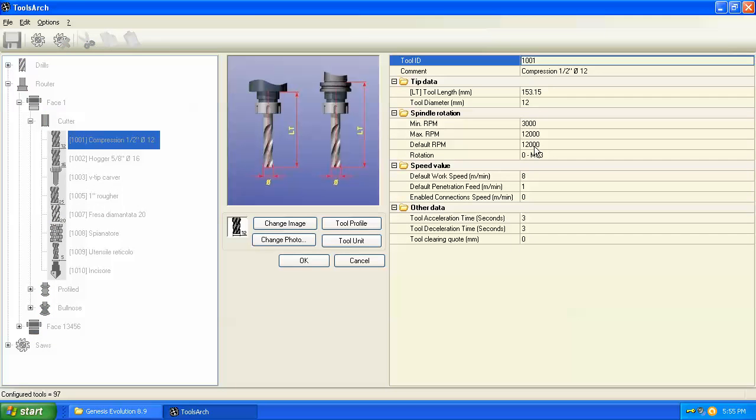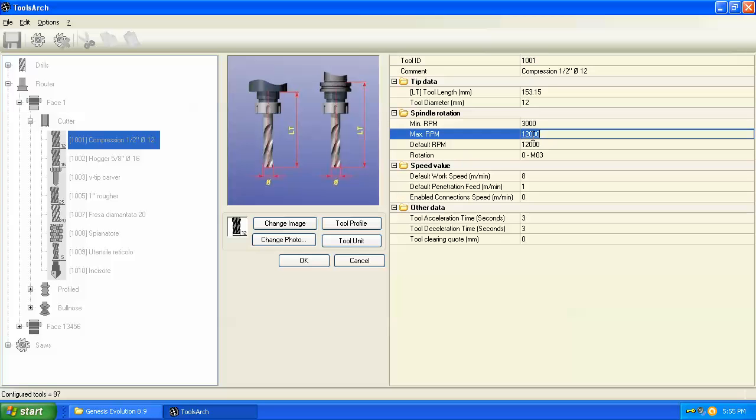But in any event, enter your tool length, your diameter, and minimum and maximum RPMs. Like drills, there's no reason to turn down the maximum RPM, which is typically 24,000 RPM. With router bits, with most wood materials, you're going to operate somewhere between 15 and 18,000 RPMs as a default, but you can go faster. It's important to always use this maximum RPM as a safety feature.